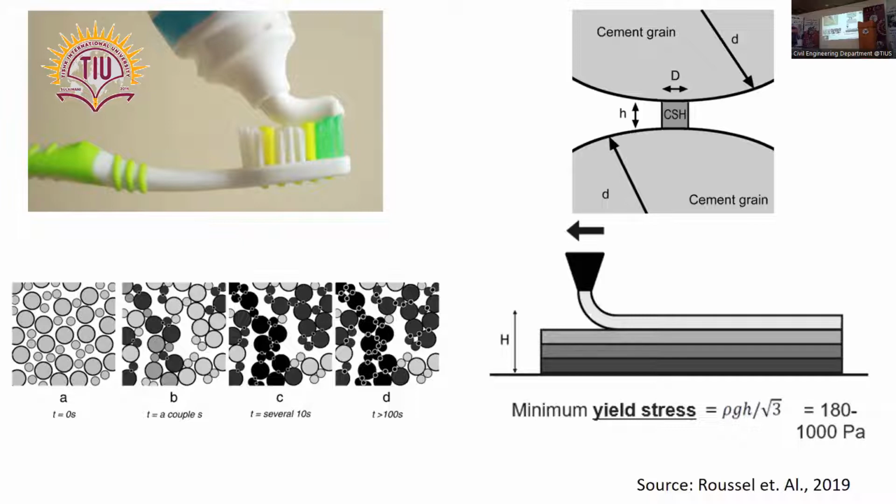But once you remove the shear force from the pumping side, then this material has a flocculation ability. It will reflocculate and gain the same yield stress, or almost 80 to 90% of before, so that you will get a stable filament. So this is a very brief scientific background of how to design the material. You have to rely on the thixotropic concept.